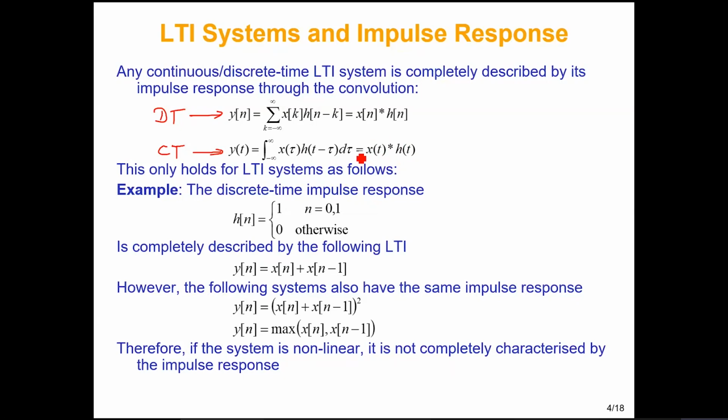Now we can either have the impulse response to completely describe the system and find the output for any given input, or we could be given a difference equation in order to find the output for any given input. Till now we have been focusing on convolution, which is based on the impulse response. So if the impulse response h is known, we can find the output for any given input.